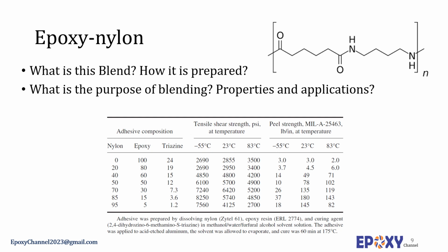The toughness associated with epoxy nylon adhesive is primarily due to hydrogen bonding within the nylon molecules. However, the high polarity that contributes to a high degree of toughness and adhesion also causes water absorption and significant loss of strength from exposure to moist environment. There is also evidence that the toughening action of the nylon is partly due to the reaction of the amide hydrogen with the epoxy ring.